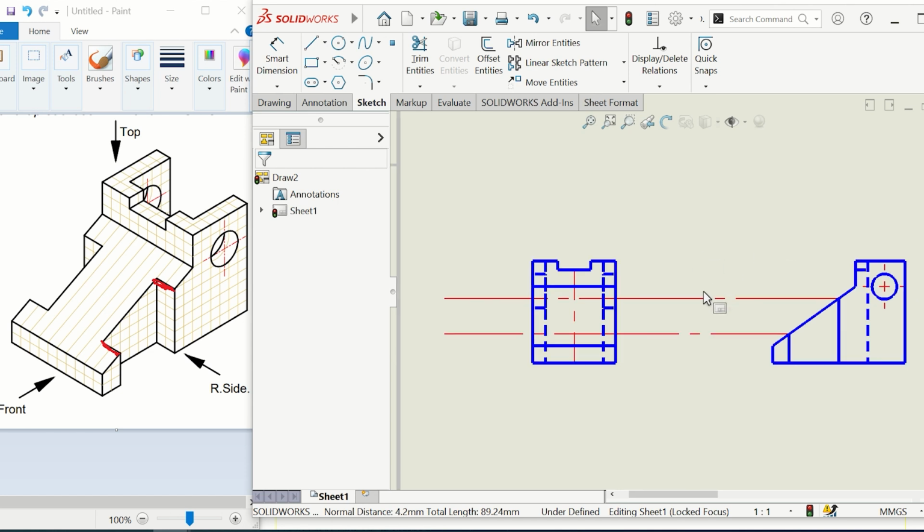Okay, well, if I draw them, of course, in the sketcher, which is what we're going to see later. In any case, now I've made them for construction, so they don't need dimensions. Okay, they don't need them, although you can dimension them. Now, the most important thing that I've done here is that I have located the position of this line and this line in the front view.